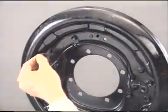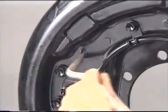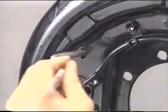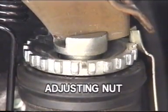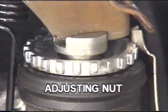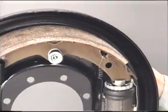Remove the shoe adjustment plug from the packing plate. Turn the adjusting nut using the SST until the wheel locks. Turn the other end of the adjusting nut using the SST until the wheel can be turned easily. Refer to the repair manual for the standard number of notches to be backed off.